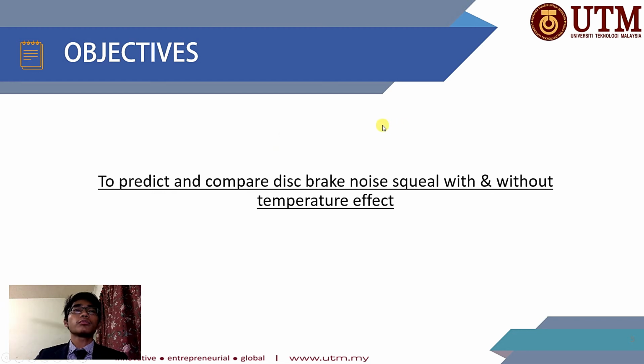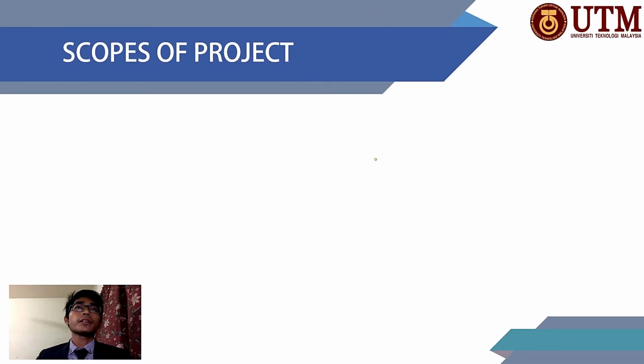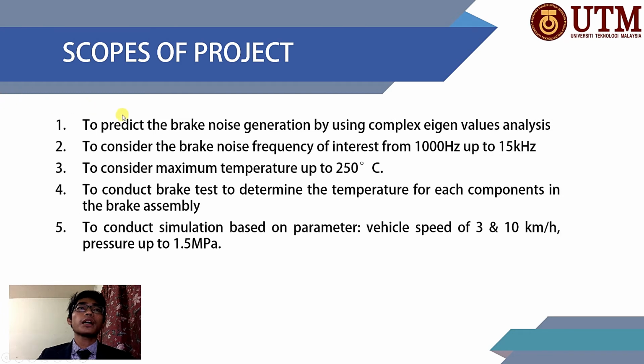So my objective of this project is to predict and compare disc brake noise squeal with and without the temperature effect. And the scopes of the project are these. The first one is to predict the brake noise generation by using complex eigenvalue analysis. Second one is to consider the brake noise frequency of interest from 1000 Hz up to 15,000 Hz. The third one is to consider maximum temperature up to 250 degrees.